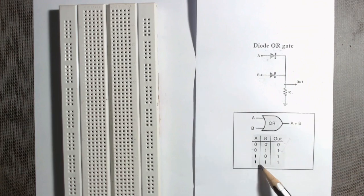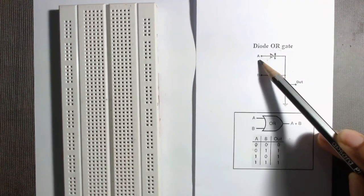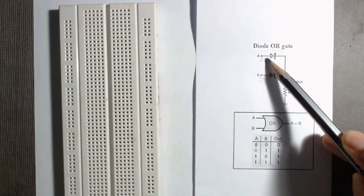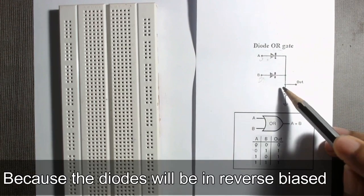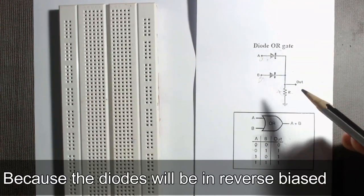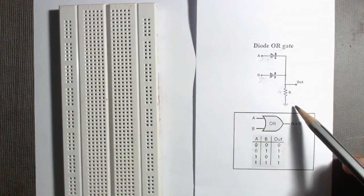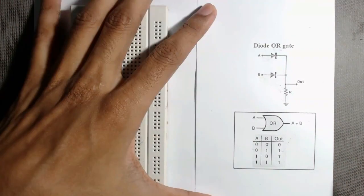So from this truth table of the OR gate we can see when we apply 0 at terminal A and 0 at terminal B, there will be no current through these diodes, so there will be no current through this resistor, so we will not get output voltage across this resistor. That's why the output is 0 in this case.